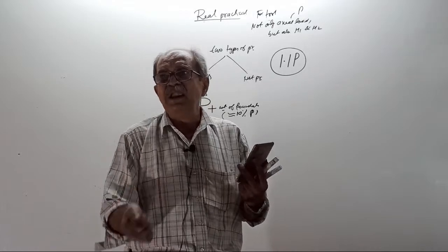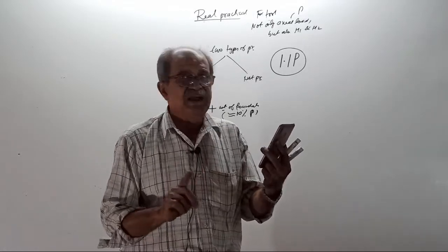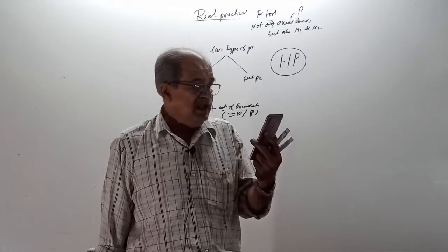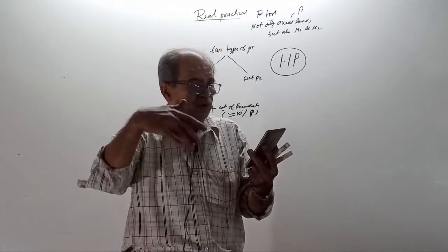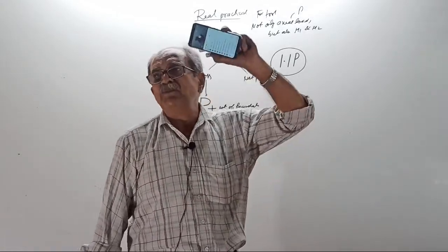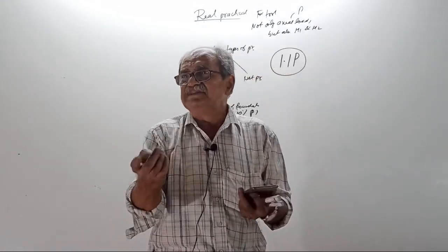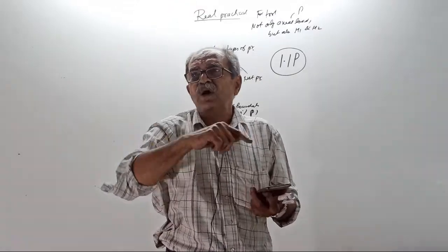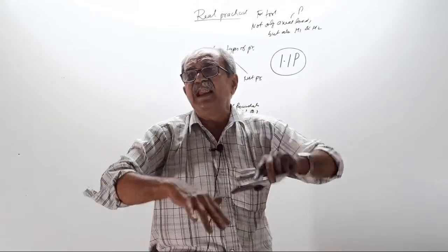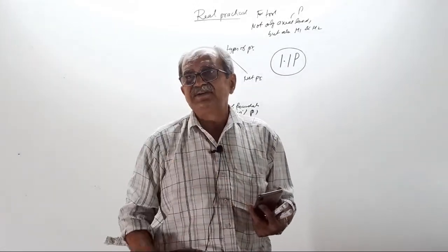You assign only column load. Don't give 10%. Why? Reason. Self weight of footing, ETABS will calculate. Clear now? So when ETABS gives pressure, it will consider not only column load but also the weight. But if heavy earth filling is there, then you have to give extra weight.